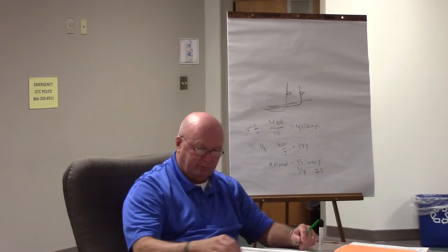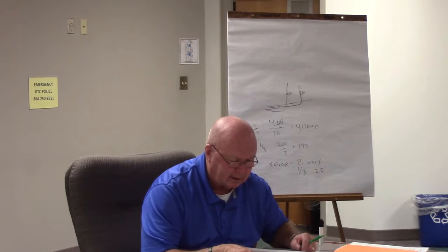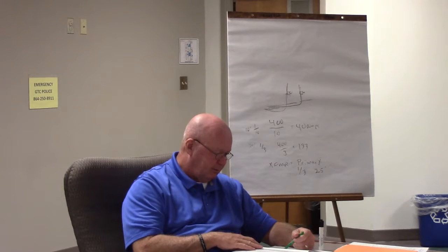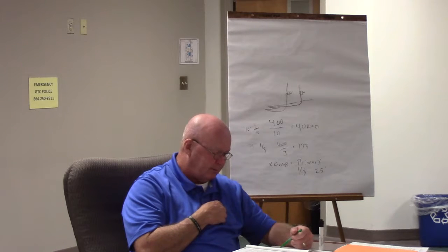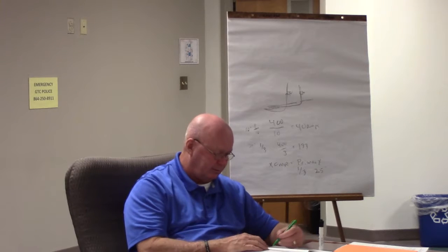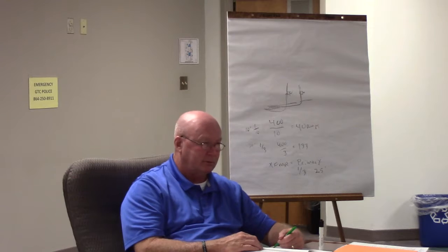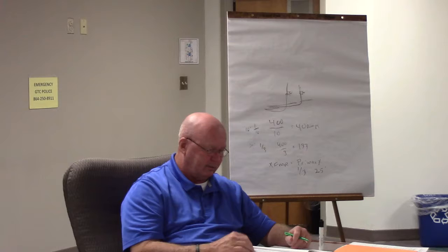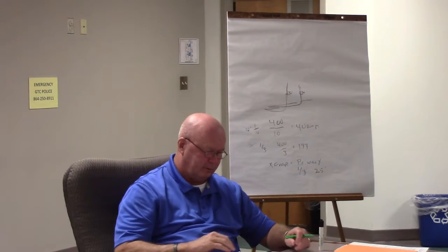Now, C6, if we look here in the code book, C6, secondary conductors over 25 foot. C6 will permit conductors from a transformer in lengths up to 25 foot when these conditions are met. The ratio of the primary and secondary voltage is multiplied by 1/3. Sound familiar? The secondary conductors terminate in a single circuit breaker. Sound familiar? And the conductors are protected from physical damage. All right. So look at a couple of examples here they got in the book.